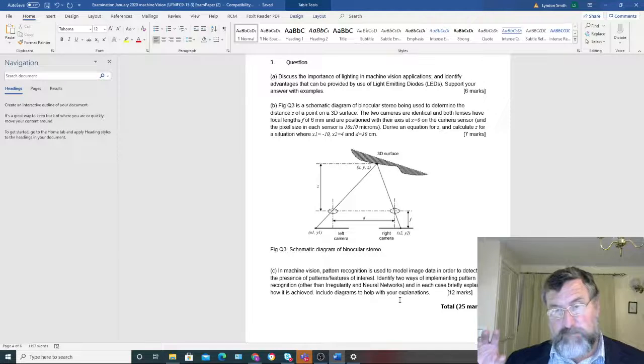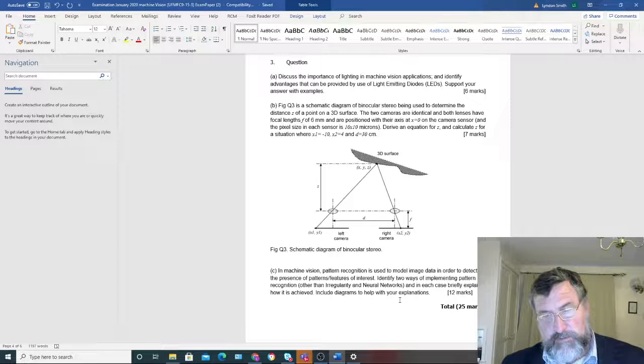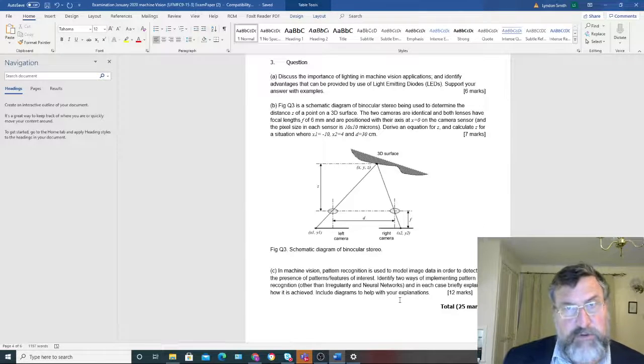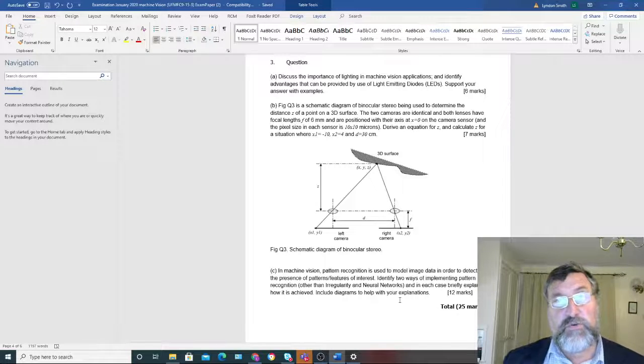You rig the camera up such that it's looking at the specular or mirror type reflection of that light. Then you see a bright line corresponding to the fluorescent tube. Any little defects, scratches and so on, tend to scatter the light and they appear as little black marks. That's called bright field illumination. That's very commonly used, especially when you've got minor defects on surfaces like that, and you need an extended source, such as a fluorescent tube, to do that.